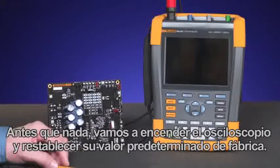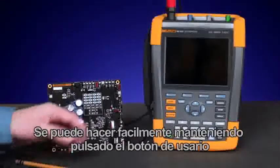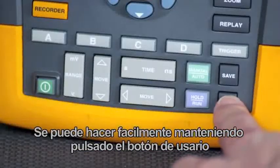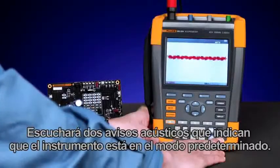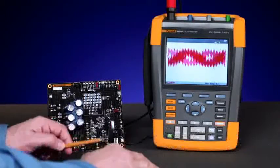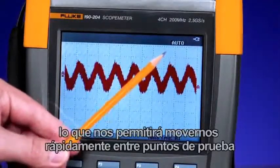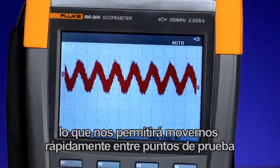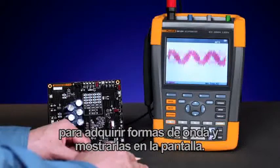First off, we're going to power on the oscilloscope and reset it to its factory default. This is easily done by holding down the user button and then powering the instrument on. You'll hear two beeps indicating that the instrument is in default mode. We do this to make sure we're in the auto connect and view mode, which will allow us to move quickly from test point to test point to acquire waveforms and display them on the screen.